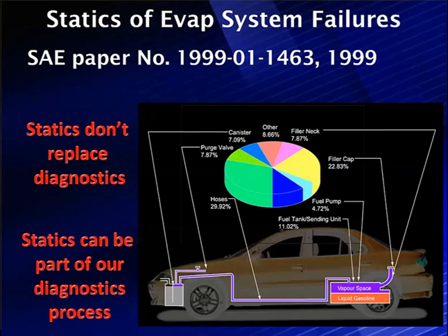That means 77% of the time, it won't fix it. Let's say that again. Statistically, 77% of the time, you're not going to fix the car by changing the gas cap. And how are you going to know you didn't fix it? You're going to give it back to the customer and have them come back later? If you want to go statistics-wise, change the hoses.